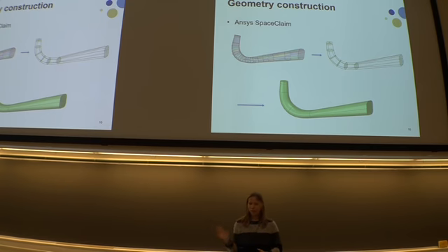But the final way I figured out to do it was to construct a few cross-section surfaces of the draft tube, and then draw polynomial lines, and then use a blend tool to create a volume. So the last picture is showing the final draft tube I've used for my simulation.